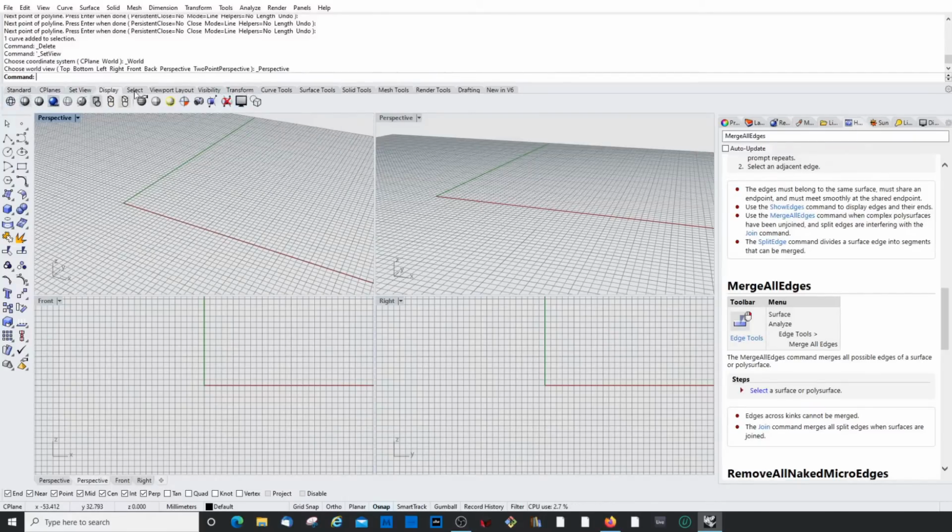Display, we also saw that. So it's basically, you could say, in the standard panel, there are the objects which you probably use most, and then in here you have tools specific to a specific topic. Viewport layouts, visibility. So there's hide, unhide, hide only selected or show only selected objects, and so on.